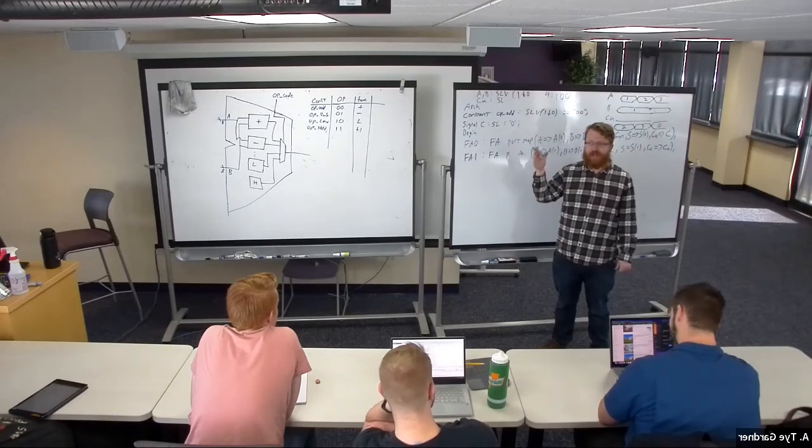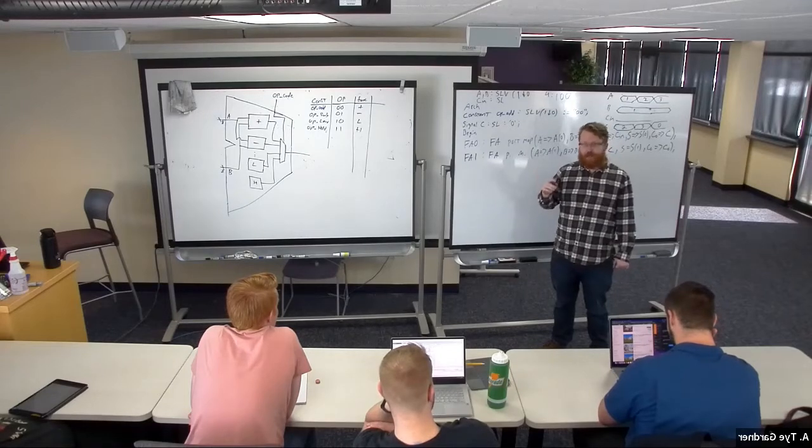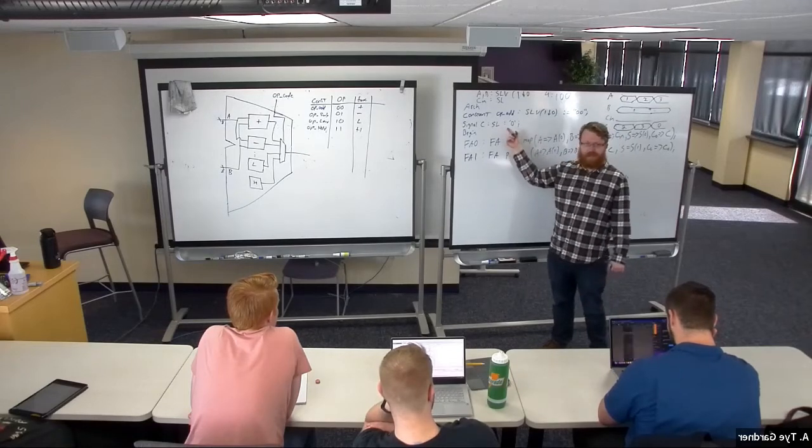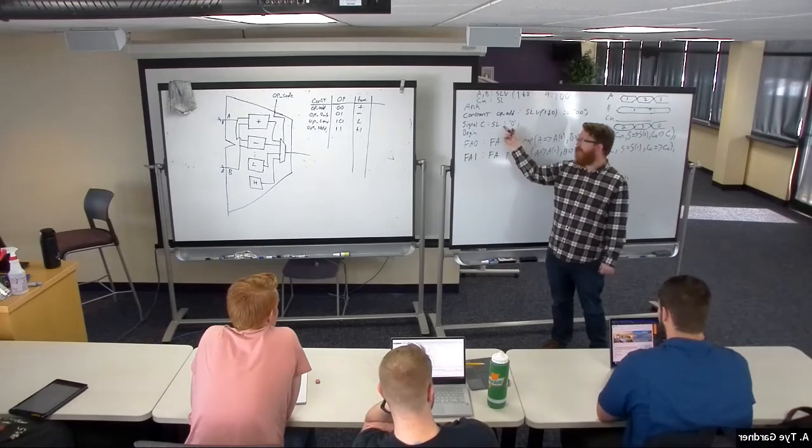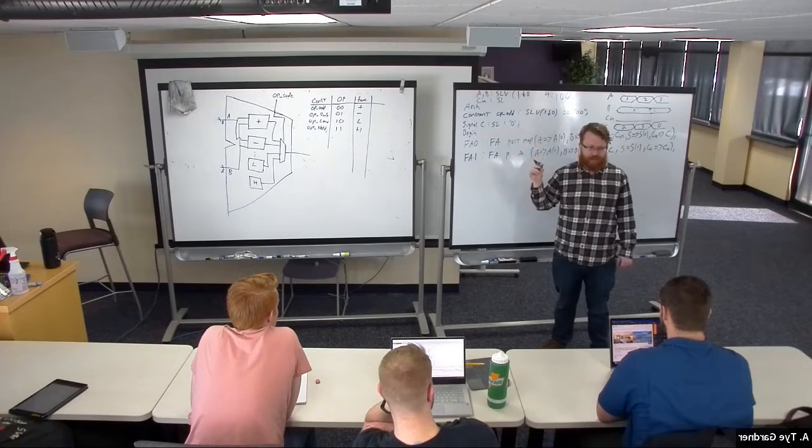That default value doesn't synthesize, is what it's called. So signals, we don't like to do this. You are going to be tempted to make your simulations work, but if you need this to make your simulation work, then your code doesn't actually work. Okay.